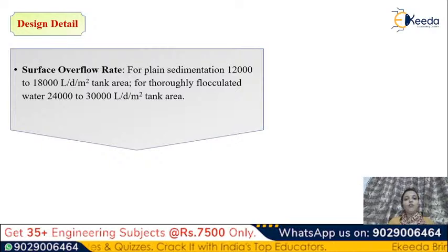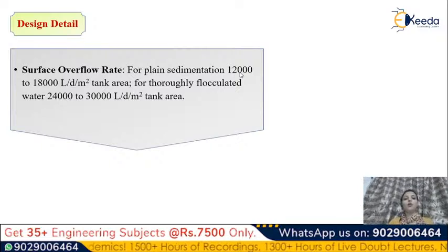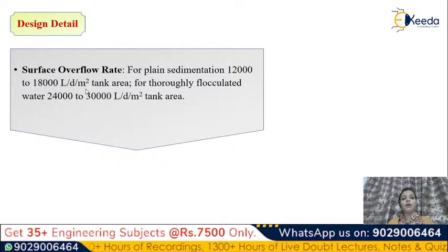The surface overflow rate for plain sedimentation is 12,000 to 18,000 liter per day per meter square.